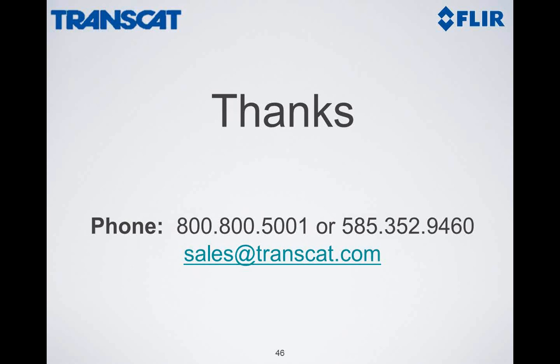Unfortunately, there's no set good emissivity value since you have so many different materials or different shininess. But if it's weathered, if it's oxidized, meaning if it's been outdoors, that would always raise the emissivity. But there's no rule of thumb of what's a good emissivity. Now, I've noticed many consultants and people out there set the emissivity default to 0.9 as a general rule of thumb or point of reference.